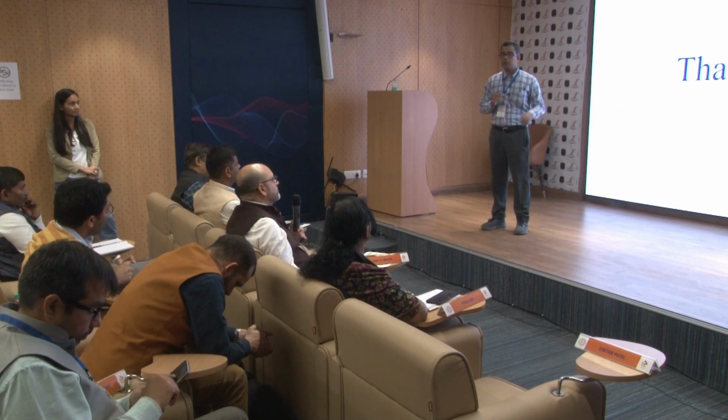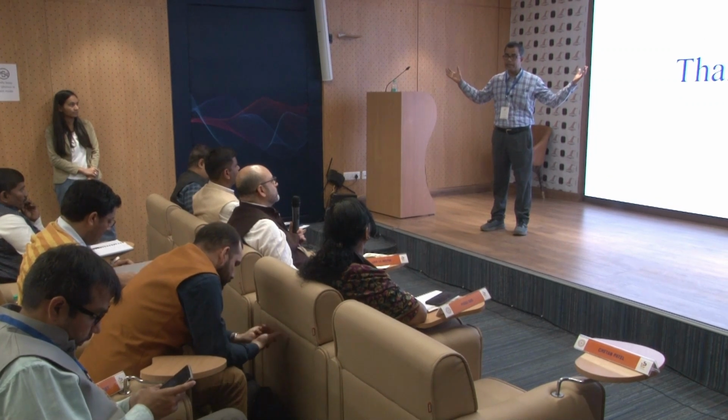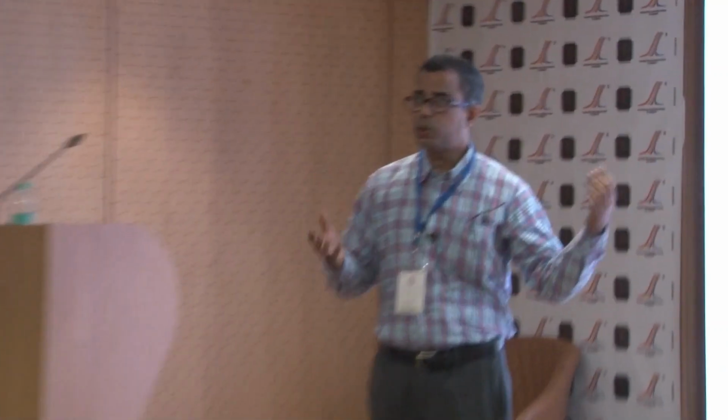First of all, packaging is the most important. We cannot have a wide diameter of the actuators. So how much the actuator diameter has to be depends on the pressure and the force, and it has to be fast enough, because if it is not very fast, our system is not going to survive at very high speeds, because the response will be very low.